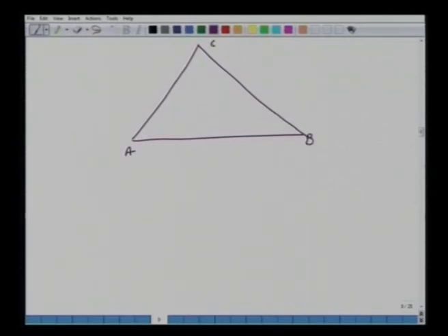In this case the raffinate phase concentration is given as 15%. So if this is 90 to 10 increasing in this direction, somewhere here we have to read 0.85, and then read across like this, so on this equilibrium phase you will have the line like this.